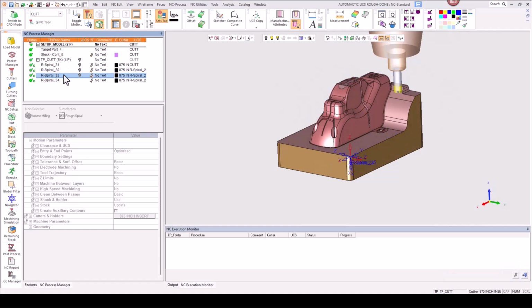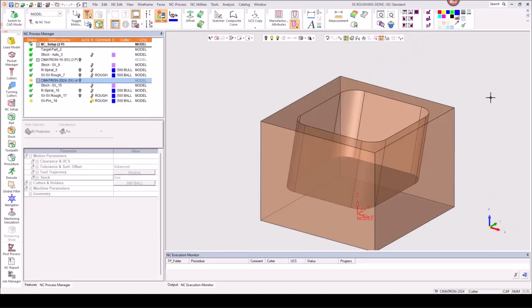And it's also very easy to switch this tooling, have it bring in all our settings for horizontal, vertical step, speeds and feeds. All of this can be automated. So very quickly we can start removing material with the shortest possible tooling, keep things rigid, keep them moving fast, very easily.